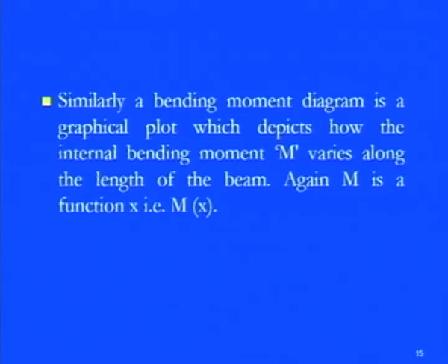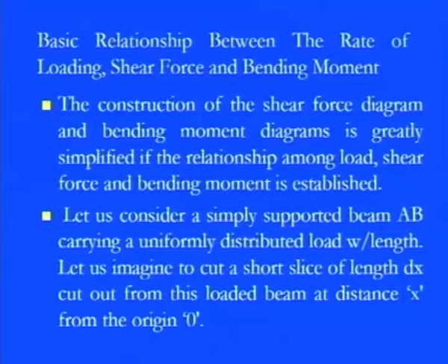Similarly, a bending moment diagram is also a graphical plot, or graphical presentation, which depicts how the internal bending moment M, or B.M., varies along the length of the beam. And again, since we are taking the individual sections of this beam, M is also a function of X. So whether it is the shearing force or the bending moment, since they are functions of X, how they will vary is now our matter of concern.